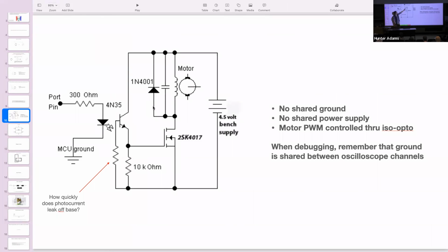And this is because if we're pulse width modulating the motor on and off, the inductive element in that motor will produce very large voltage spikes of opposite polarity. And so we have this snubber diode in essentially all motor driver circuits to allow a safe loop through which that reverse polarity can travel without destroying anything else. This integrated circuit does have inbuilt snubber diodes. It does not, to my knowledge, based on my reading, have an inbuilt bypass capacitor. So that one you breadboard externally.